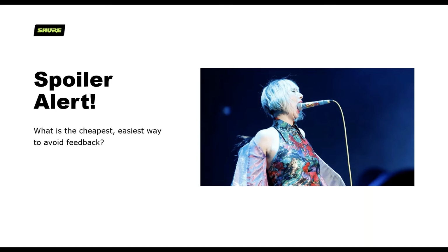And the more they have to turn it up, the more likely it is to get feedback. So that's why we say it's actually the cheapest and easiest way to avoid feedback, because it doesn't cost you anything to keep the microphone close to your mouth. It's free gain before feedback, essentially.